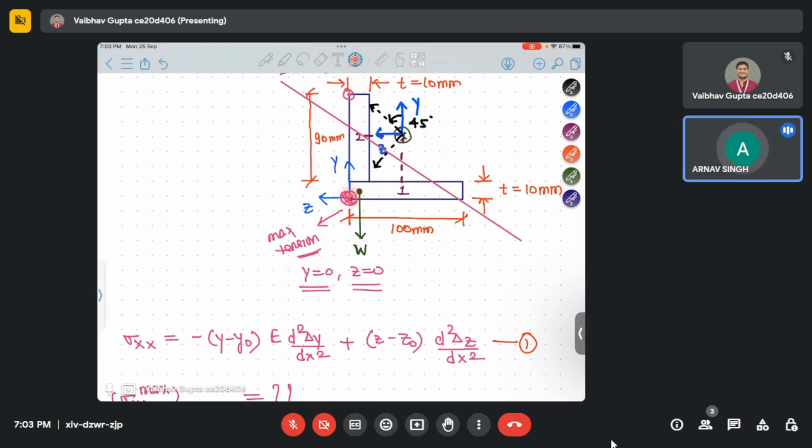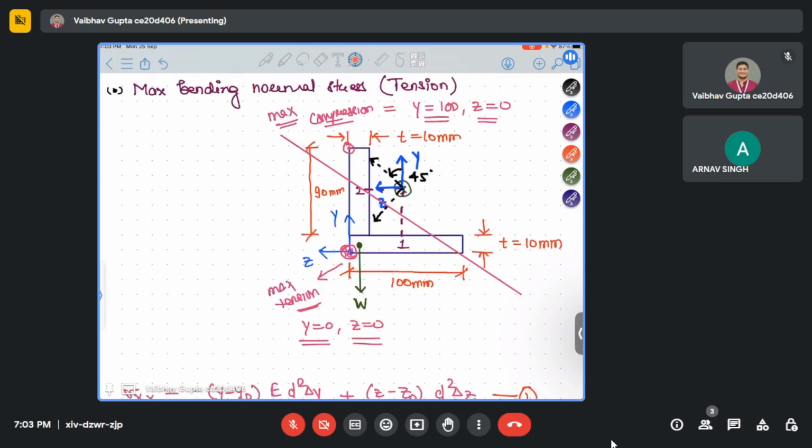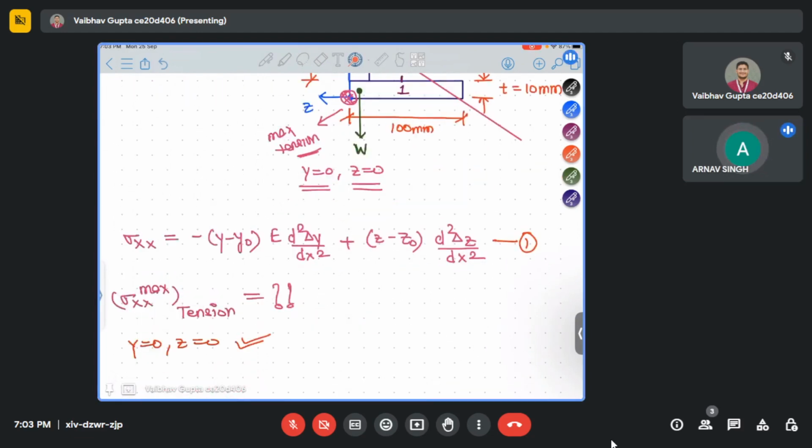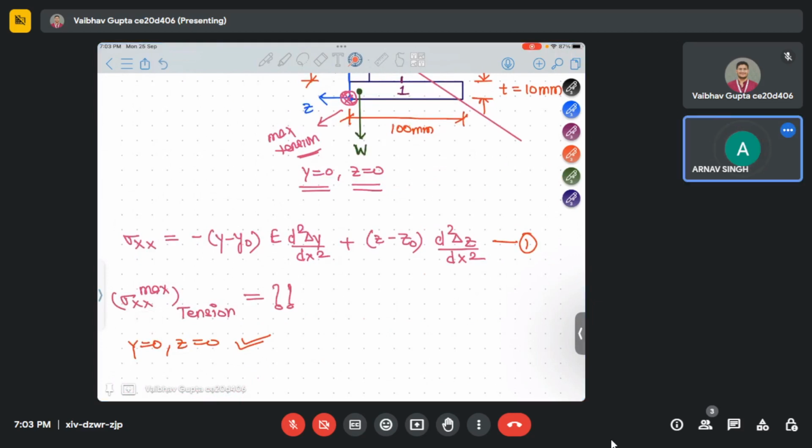सर लेकिन इसके जहाँ पे जो 1900 है अगर वैल्यू चेंज होगा तो आंसर भी change? Value doesn't differ. See, only shape and the location of neutral axis matter. For this, neutral axis location will be always like this only. So you will get maximum tension here and maximum compression here. तो मतलब सर क्या कहना चाहते हैं एक बार बता दीजिए. So here in the question अगर इसमें वैल्यू चेंज रहे, it won't change. It will be same. Doesn't depend upon value. Shape should be like this. Okay, sir. Got it?